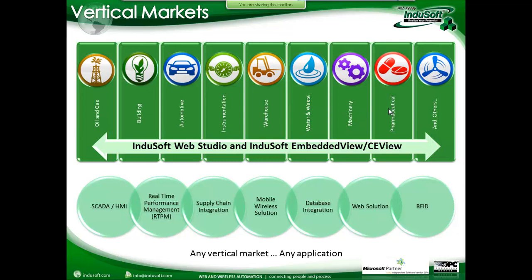To give you an example, in the pharmaceutical industry there is a U.S. government requirement called 21 CFR Part 11, or FDA 21 CFR Part 11. By implementing that, it allows the HMI or SCADA application to have features for users, passwords, logins and security, as well as traceability and the ability to challenge a user. For example, if a supervisor has logged in and walked away and a standard operator comes in and tries to use the supervisor's login, it will challenge them again. So, as well as traceability options.